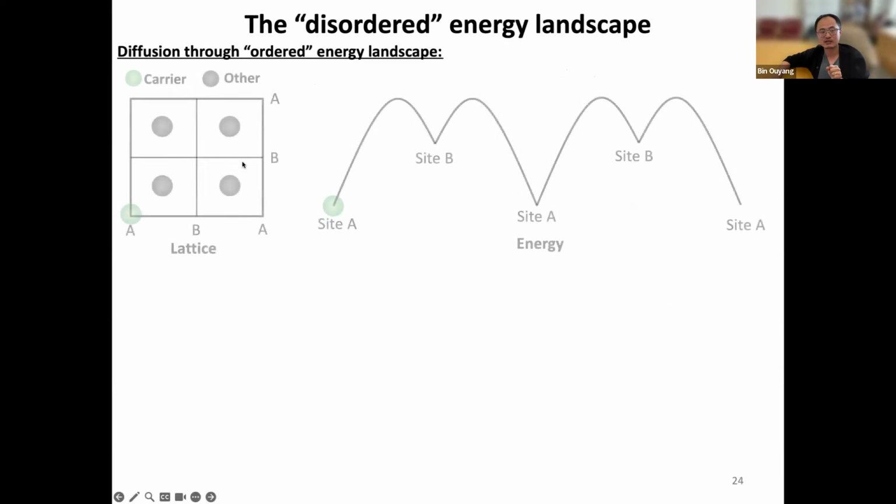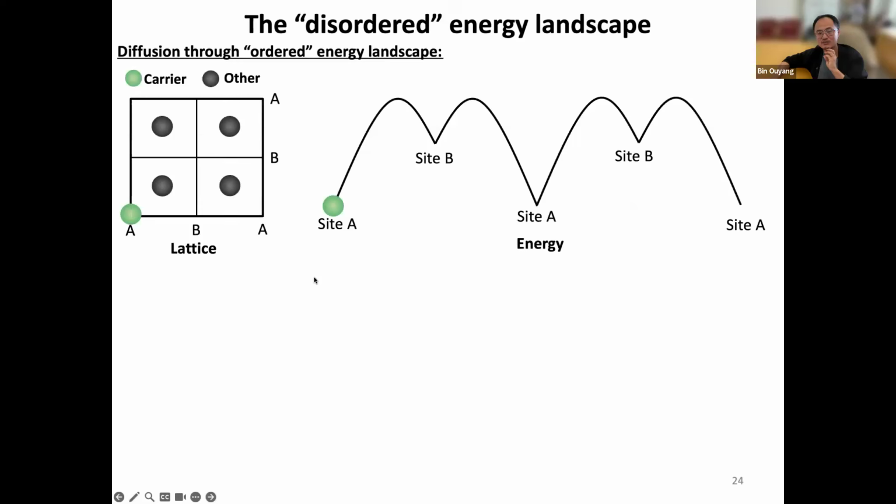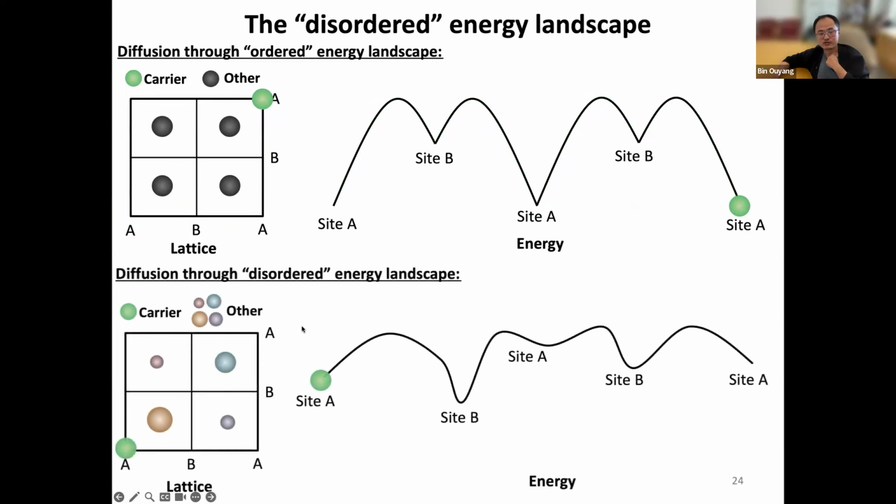Think about the diffusion, right? This is the diffusion you see in the textbook. You have a crystal lattice, you have well-defined first nearest neighbors, so your local environment is fluctuating periodically. You're going to have some diffusion barrier. That's the diffusion mechanism, and that's essentially how you calculate diffusivity. But when you have disordering, the local environment, even though it's still crystalline, you have compositional disorder, the local environment is going to fluctuate quite a bit randomly.